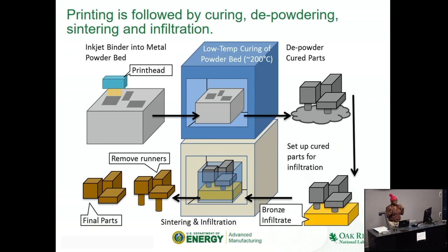Dr. Nicely, you're giving me, I'm lost, look. No, I'm just amazed it's 90% dense. How much density did you say? With binder jetting right now, because we're using powders, you end up with a 60% dense part. So you have 40% void space that you need to fill, and we fill it with bronze via the infiltration route. But you had a really high number at first, right? 90? No. Oh, no, 60, okay. I didn't hear it right. And then 40% is unfilled or void. Oh, okay.